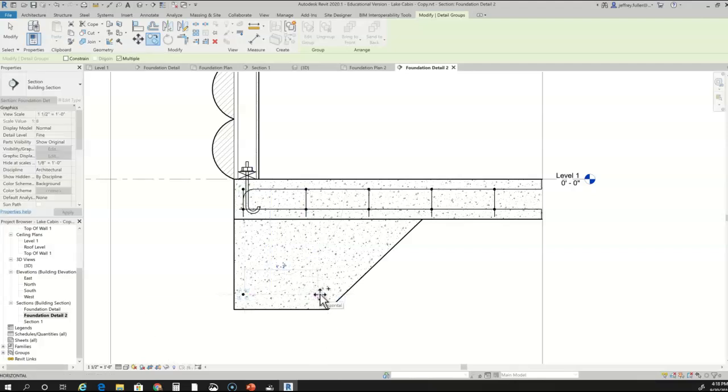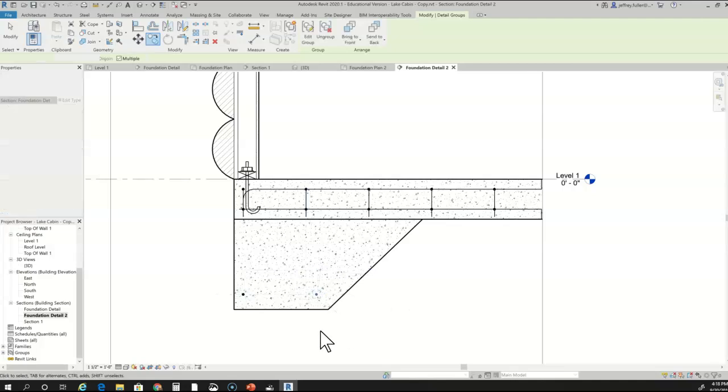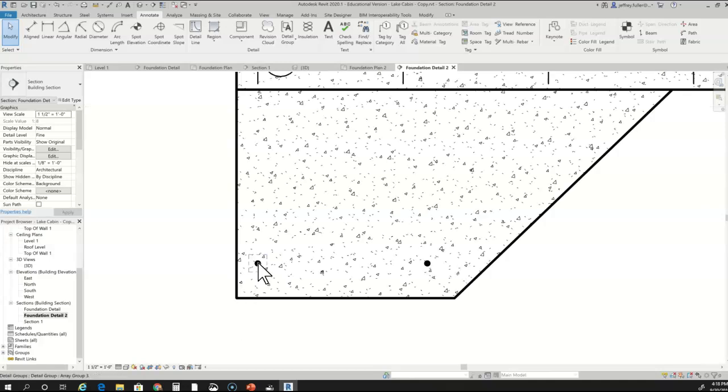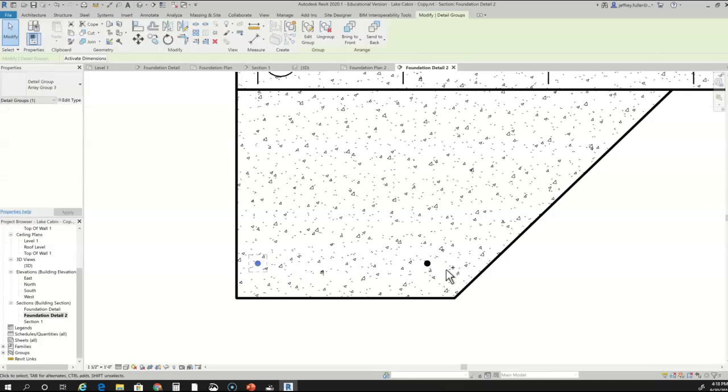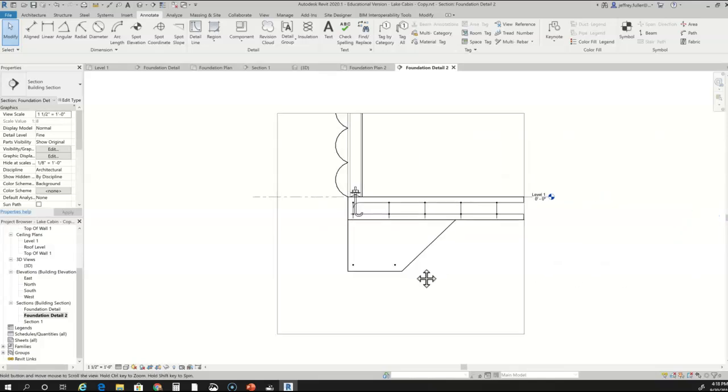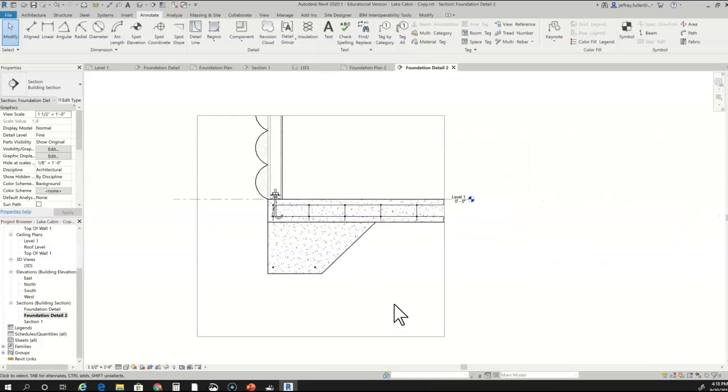And you'll probably want to go back and measure that, and then of course you could take the other one out to the side and click that one here. Okay, we're about 3 inches from the bottom, so I could actually bump both of those down about 1 inch, about right in there. Okay, so now we have the rebar that's inside of our thickened edge.